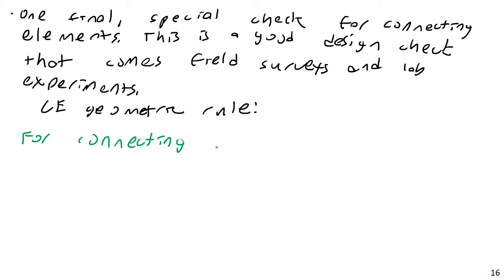That applies for longitudinal members. You do get that kind of tensile stress concentration in a long longitudinal member. But in connecting elements, we don't have that. So for connecting elements, U is essentially always 1.0, unless your connecting element is unusually long.